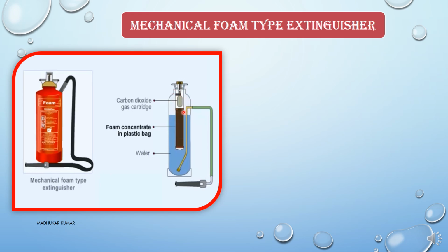Okay, so now the foam solution is ready, and due to the pressure through the dip tube, it will come out of here. Once it comes out, it creates suction pressure, and through these cut marks which you can see here, the air will be sucked inside, and the air mixed with the solution will generate the foam. You can utilize this again at the nearest bulkhead of the fire seat, and that is basically going to be completely covered by the foam solution, and the liquid fire will be extinguished.